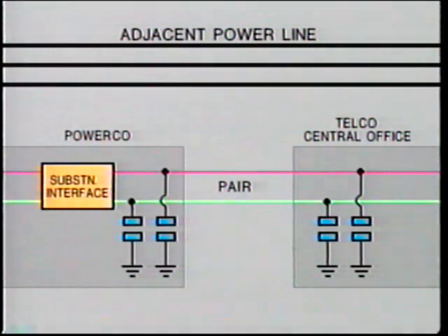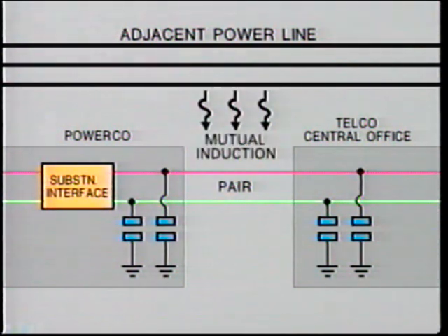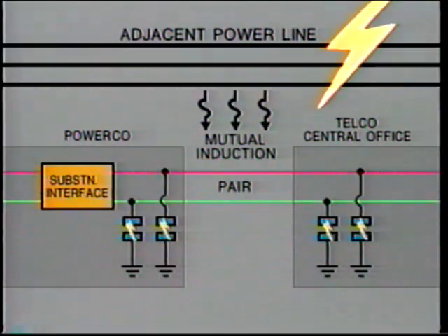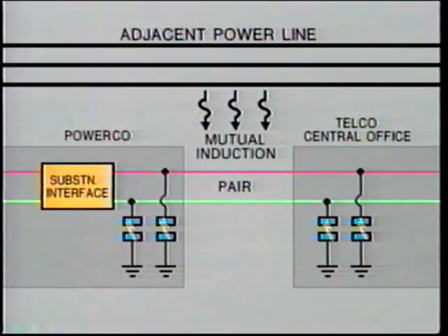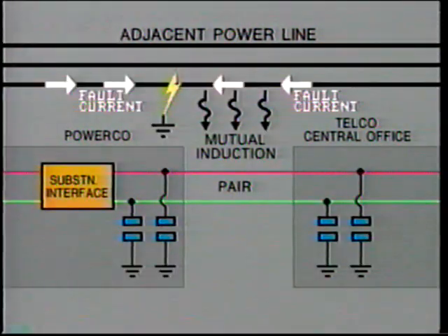The reason for this is that longitudinal voltage rise due to induction takes place in both conductors. The objective is to discharge the high voltage to ground and so protect the insulation from damage. For lightning protection, which is of very short duration, this works quite well. But in the case of a ground fault on the power line, the high current flow across the arc may be sustained for, say, 10 cycles or more.